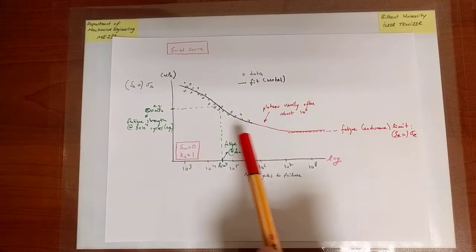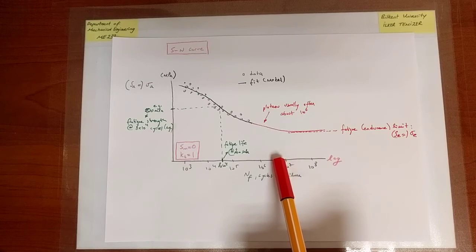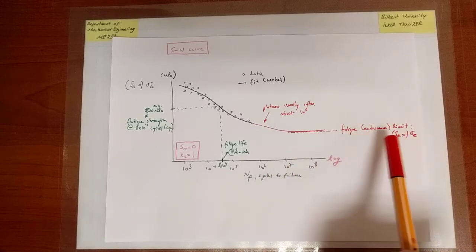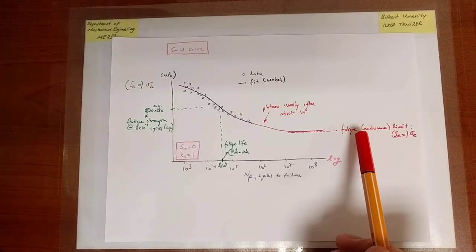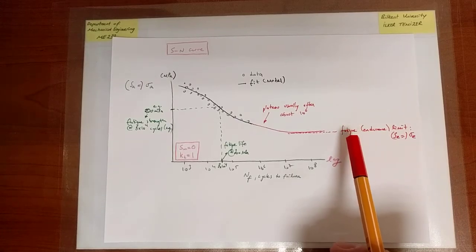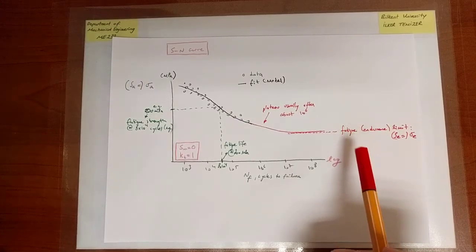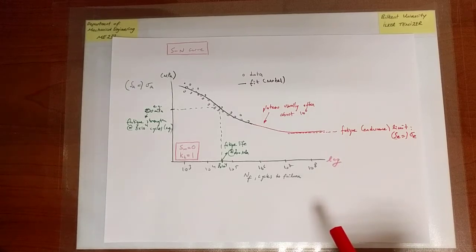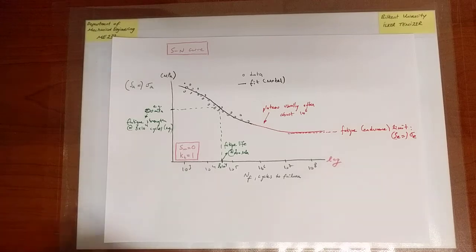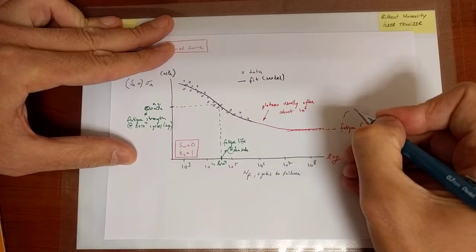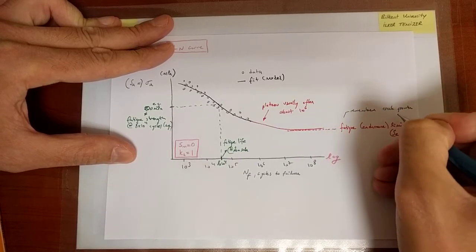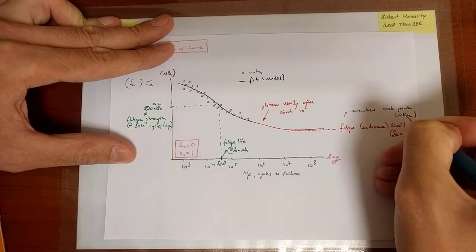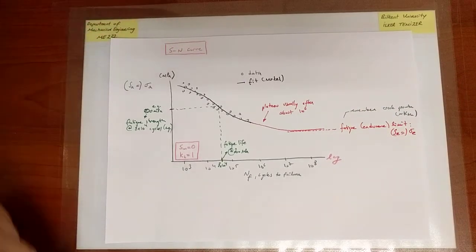Now, is this surprising? Is it surprising that below a certain stress amplitude, we do not observe fatigue of the structure? Not really, because remember, we've observed something similar in the case of crack growth. In that case, if the range of the stress intensity factor was below a certain value, which we called the threshold value, then the cracks sometimes do not grow. So remember crack growth, and in particular the threshold value.